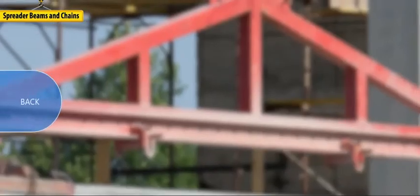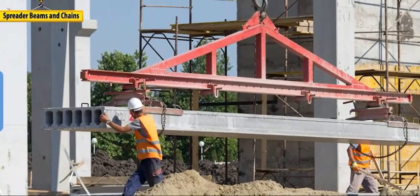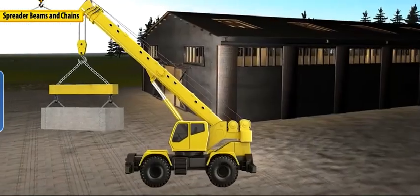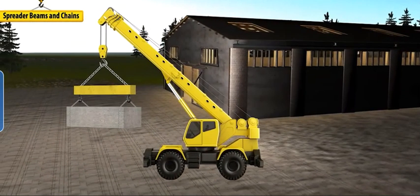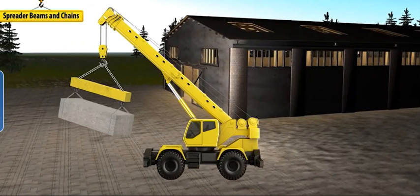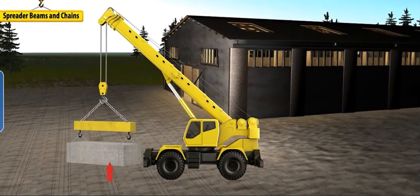Spreader beams are used to distribute the weight of loads along a beam, giving the load greater stability. The main drawback to spreader beams is that you need a lot of headroom to use one. Balancing loads can also be tricky, so as always, take the time to lift the load a few inches to check the weight distribution and make sure it is even.